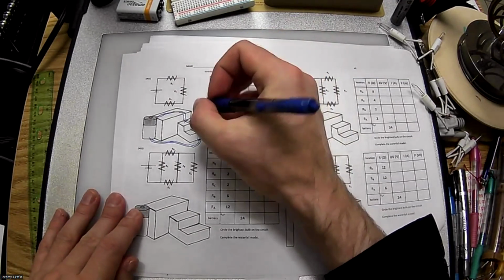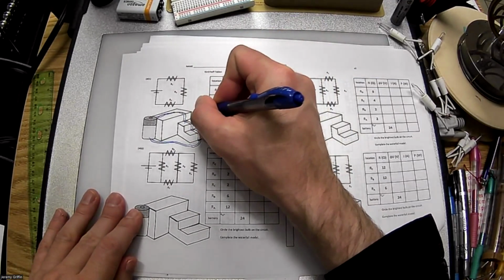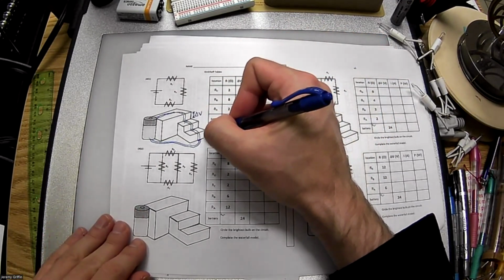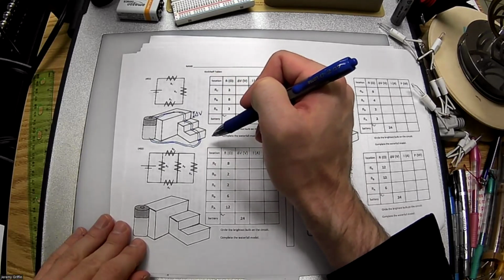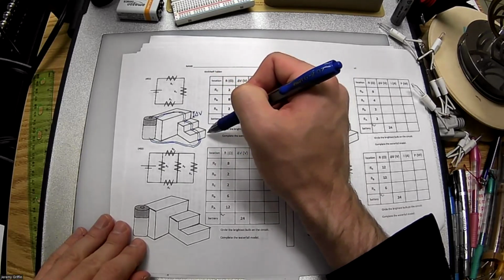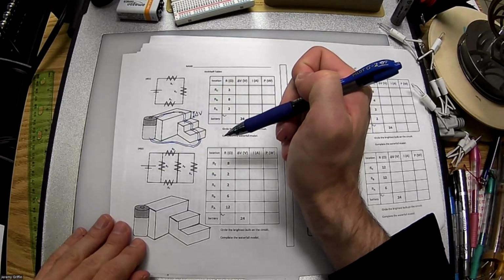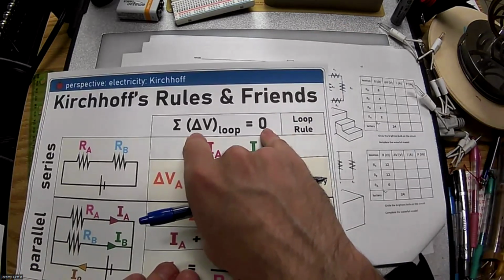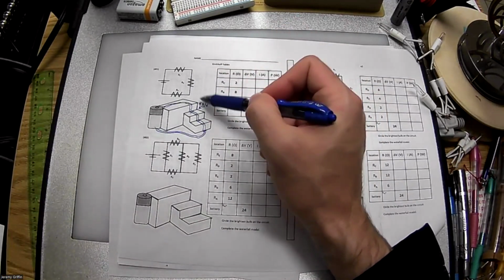In this waterfall analogy, the height of each waterfall represents the voltage drop. So I'll say delta V, like a voltage drop. Do you guys see that there's going to be 3 waterfalls, 3 resistors in series, 3 waterfalls? And the sum of the heights of the waterfalls has to match the height of the cliff that's being pumped up in the first place. By the way, that's called Kirchhoff's loop rule. So the sum of the voltages in a loop has to go to 0. So it's like 24 volts up and 24 volts down, 24 up, 24 down.